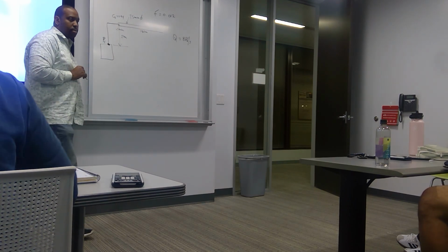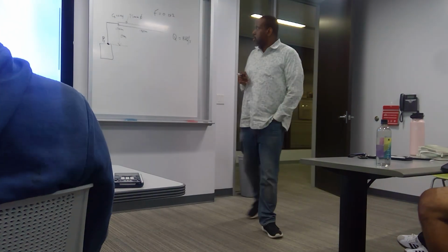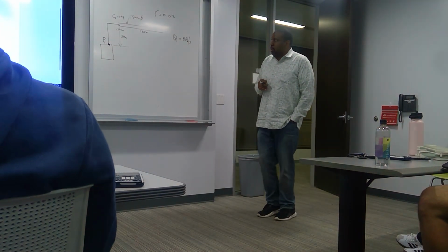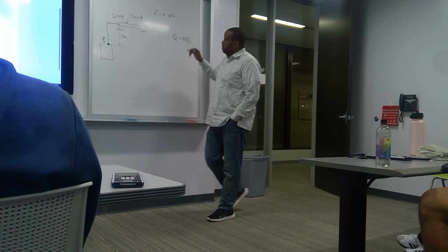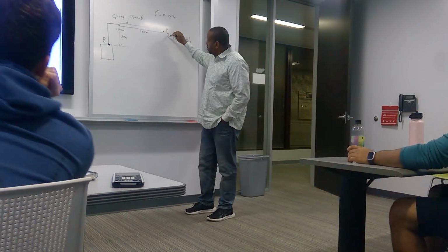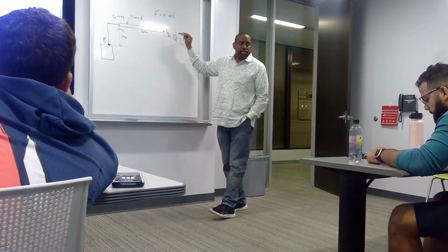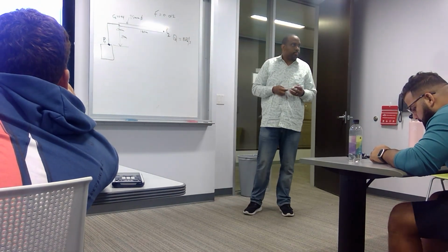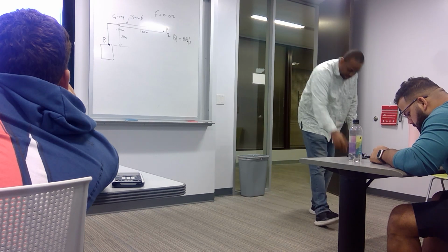So what I'm trying to do is this: this is my P1, this is my P2 here. What's the pressure at P2? Zero, it's discharging to atmosphere.